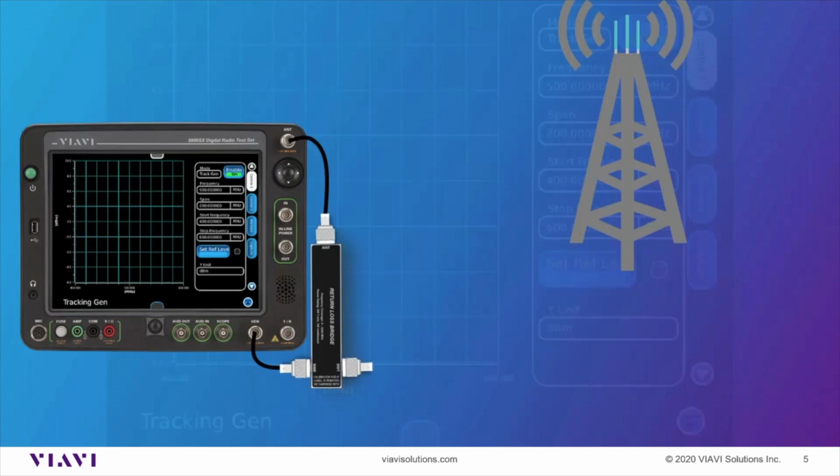But of course, ours is not a perfect world. So what can happen is you can end up with impedance mismatches along the way, whether it's a bad connector, corrosion, or a damaged antenna. And at that point, the transmitted signal can't get out the antenna, or not all of that signal can get out the antenna. Power cannot just disappear. The power that is not transferred out the antenna has to go somewhere, and it travels back down the transmission line into the transmitter, which can cause damage to the transmitter.